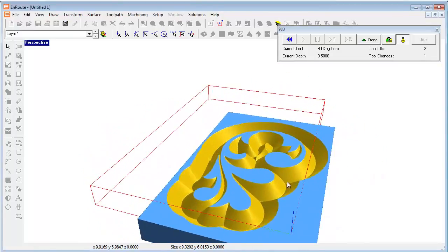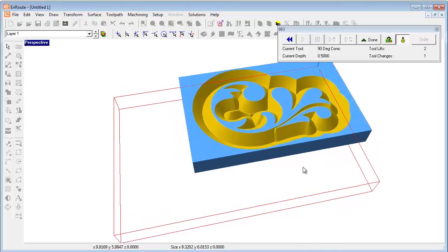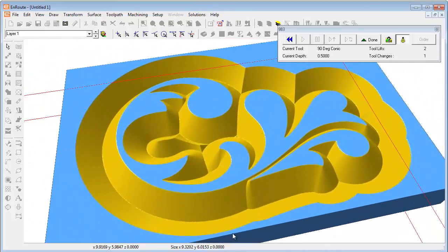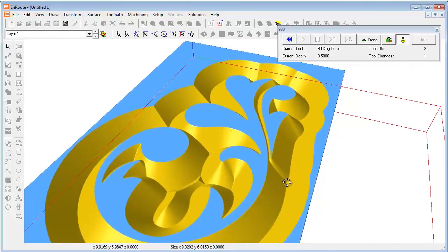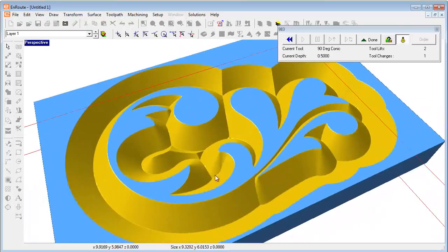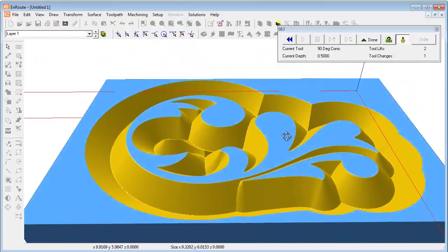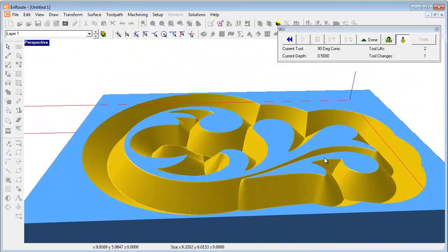So there you see the geometry. My original geometry serves as the interior, and those beveled tool paths went to the outside. So that's an external 3D engrave. It does essentially the same thing, it just goes to the outside instead of to the inside. But you can see that it finds the center between whatever geometry is appropriate, and that's where the toolpath goes, and then goes up into the corners sharply to create a really pleasing effect.